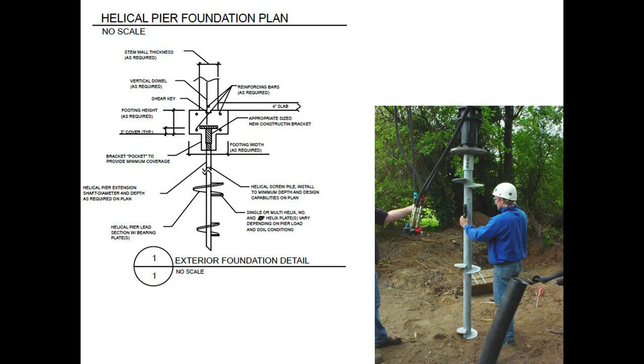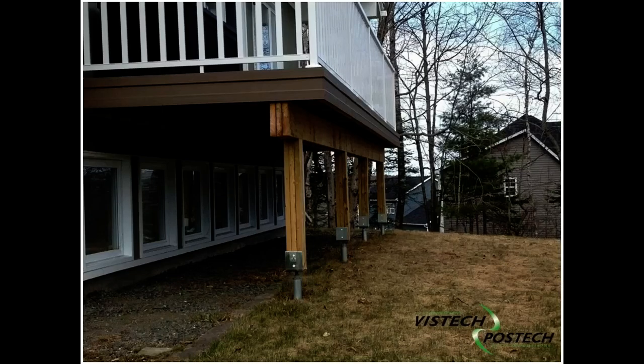So even for fairly lightweight structures where you have point loads, say a lightweight timber building, a helical pile could well be your solution. And here it is, carrying this nice little timber structure with these metal shoes, proud of the ground again, because we don't want the timber touching the ground, do we?